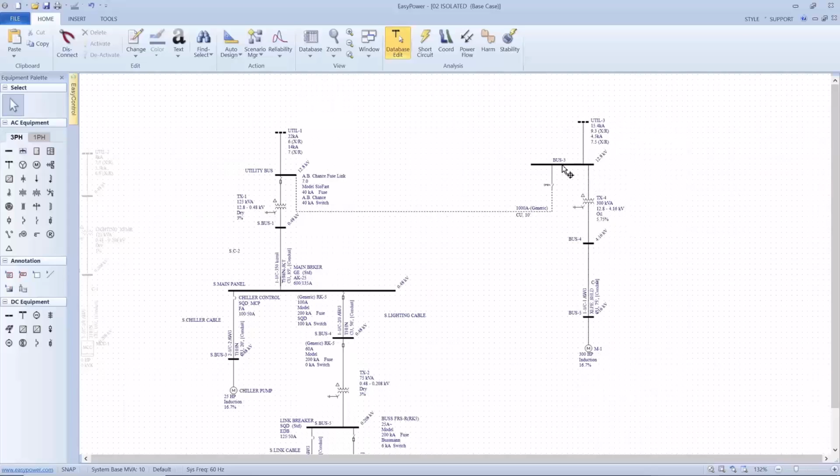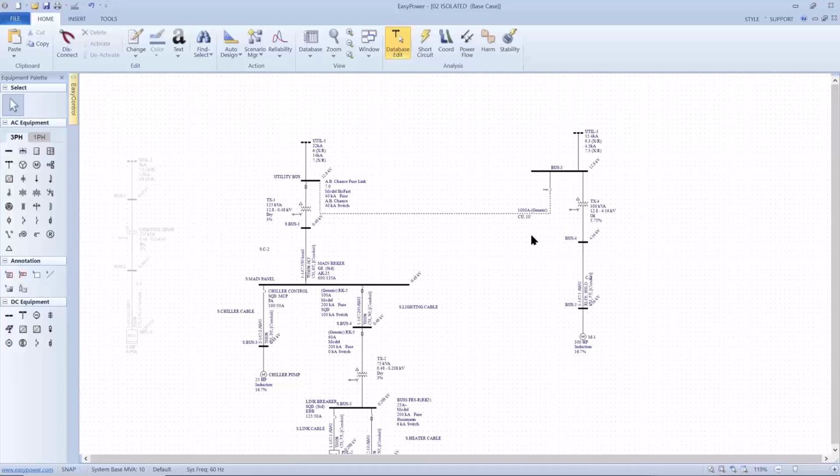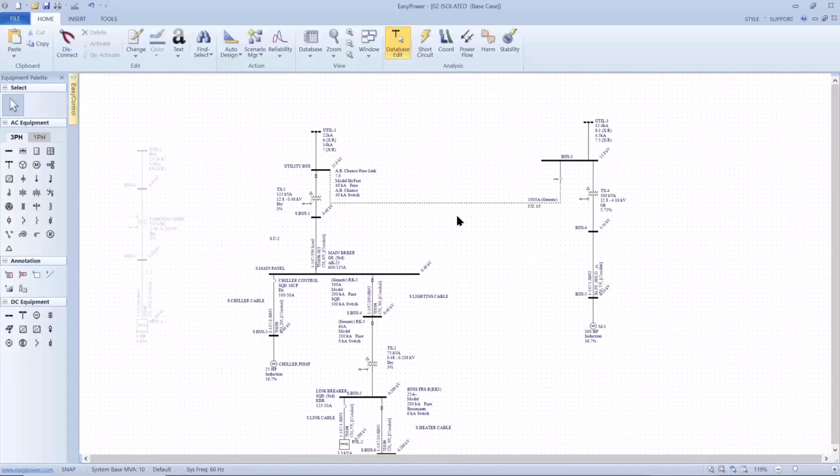I'm connecting the 12.8 utility to the 12.8 utility. What this allows are different utility connections with different utility data. So in this case, this utility connection is 22,000 amps. Over here, we've only got 15,000 amps. And the systems are in the same location, but they're not physically connected.